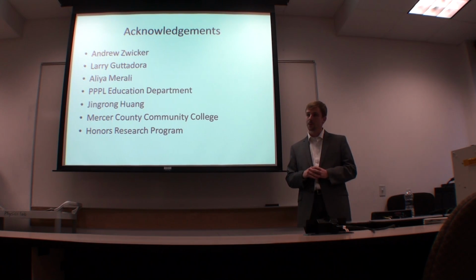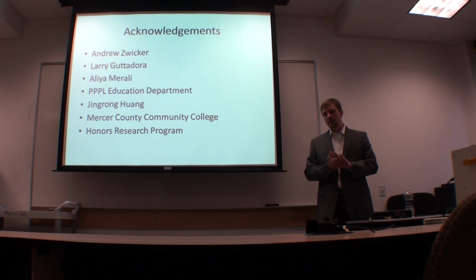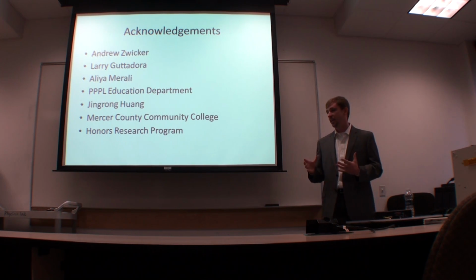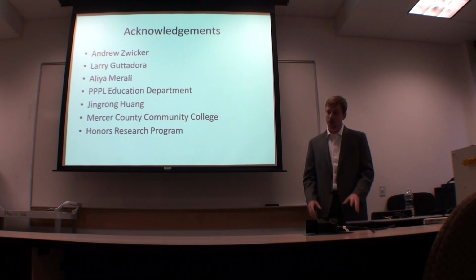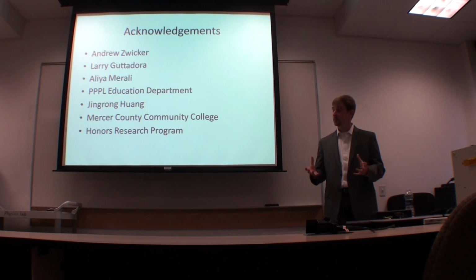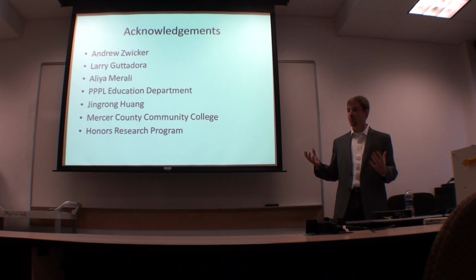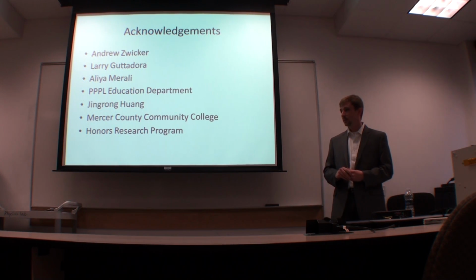Sean, what's the advantage of a plasma speaker versus a traditional type of speaker? Well, there's a couple of advantages. Essentially, the fidelity is a little bit crisper because plasma allows you to very precisely replicate music. I've read some things about how there would not be degradation of the diaphragm itself over a given time. There's actually some disadvantages to it, it replicates higher frequencies a lot better. If you think about low frequencies, you need like a subwoofer, which is a much bigger diaphragm. So that is actually why we're going to build the biggest possible plasma speaker, to hopefully move a lot more air and be able to create some of the lower frequencies.